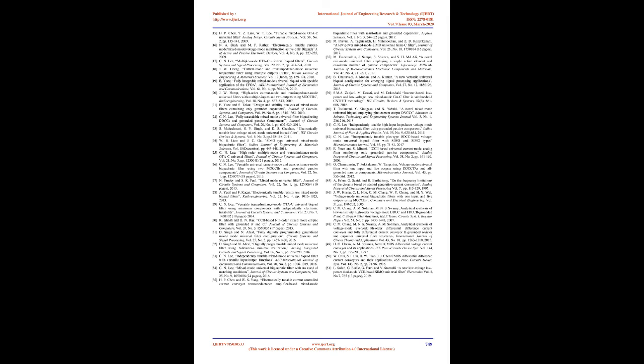To verify the theoretical analysis of the proposed general mixed-mode universal biquad filter, the HSPICE simulations with the NMOS transistor aspect ratios W/L = 5μm/1μm, and PMOS transistor aspect ratios W/L = 10μm/1μm, of Fig 2, using the TSMC 0.25μm process for the proposed circuit of Fig 1, were performed with the component values C1 = C2 = 4 pF and R1 = R2 = R3 = R4 = 10 kΩ, for the general mixed-mode universal filtering responses, leading to a center frequency of f0 = 3.9789 MHz and quality factor of Q = 1.